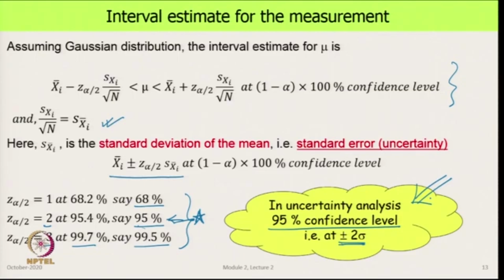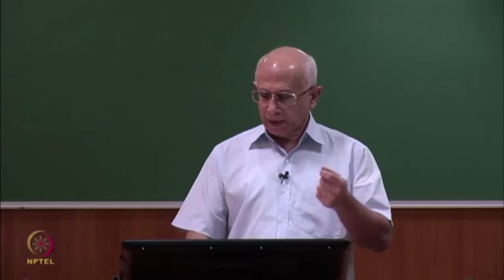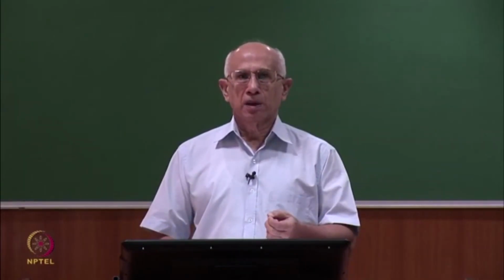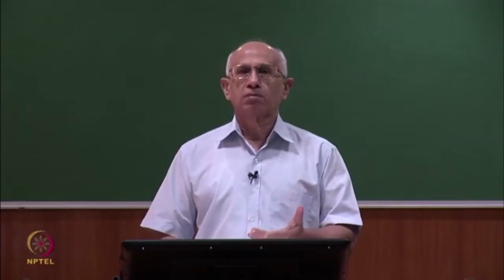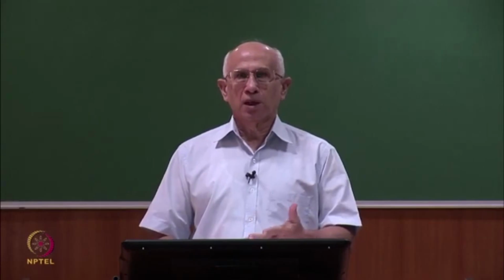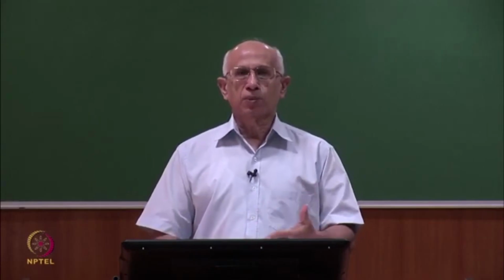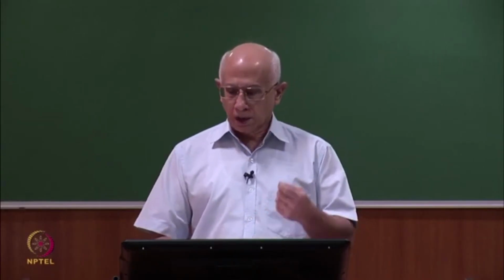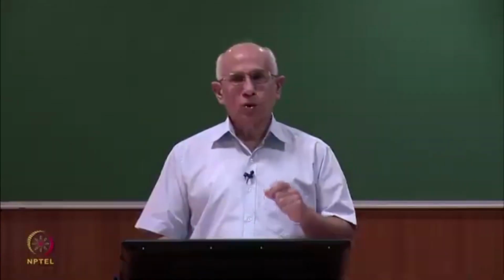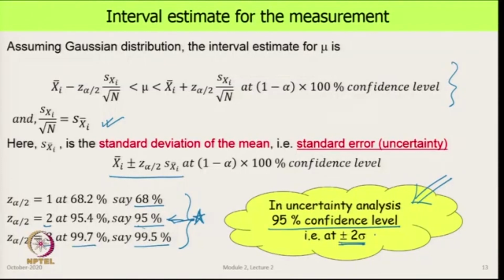So, at this point, even if you look up, say, the specification of an instrument, there will be manufacturers who will quote that the accuracy is this much in bracket at 2 sigma, or they will say that linearity is this much, and they may not tell what it is, but if you see which standard it conforms to, it will be ISO GUM or PTC 19.1, in which case it is all being referred to at 95% confidence level. So, that is how important this is.